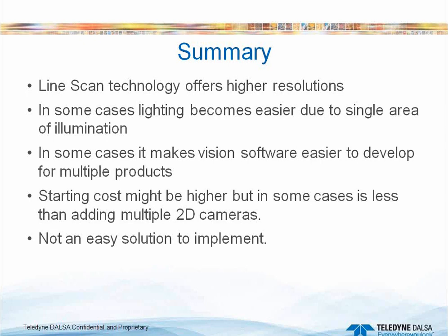They're not easy to implement. It's not as easy as you point, you take an image, you light it up, you do inspections. Again, you have to consider your motion and all your product presentation, and you have to have your motion synchronized well with the camera so that you get a correct aspect ratio, especially if you have to do any kind of measurements. And that's all I have for today.